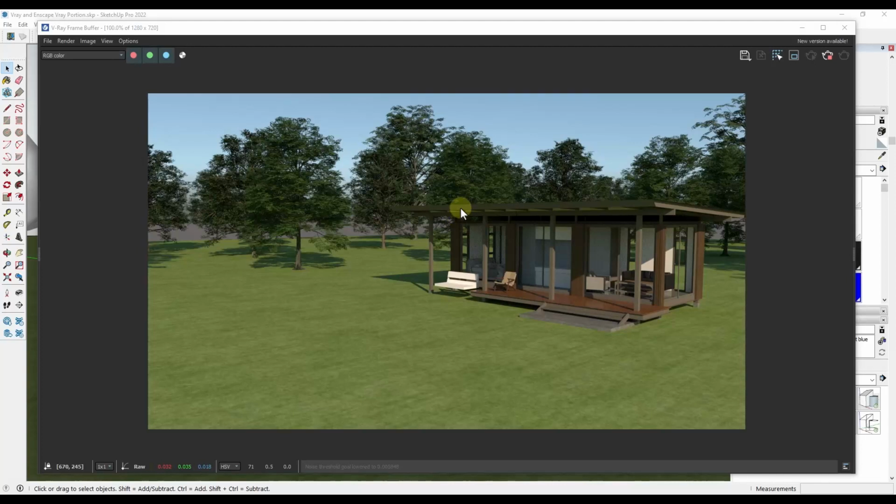All right, so the first thing you're going to notice when you open this up in V-Ray is that it's actually rendering out all of those Enscape materials and trees as well. So you could just use V-Ray, which has some different options for sizes and other things like that, in order to render this out. Or you could also replace these with the V-Ray library objects, which are higher quality, at least some of them. But in this case, what we're probably going to do is swap out a couple of the models in the background. We're going to add V-Ray grass, because notice how the grass isn't rendering out, or V-Ray fur as grass. And then we may also change out some of the materials as well, because V-Ray has a little bit deeper material library.